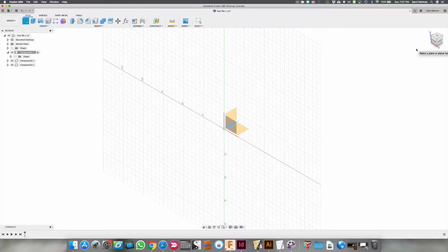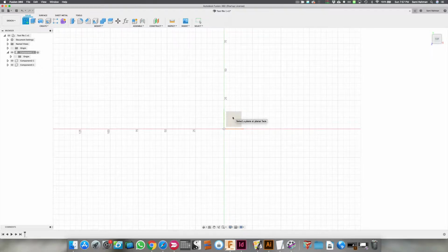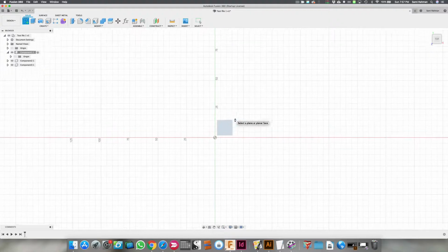The easiest thing to do is say, I want from top, then I would just go up here and click the top button. You now know the only square you can touch is top. When I click that square, you're going to see a lot of things change. You're going to see this menu bar change, and you're going to see something pop up here on the right-hand side. So let me click this, and I've now told it that I want to do a drawing, and I want to do it on the top view.